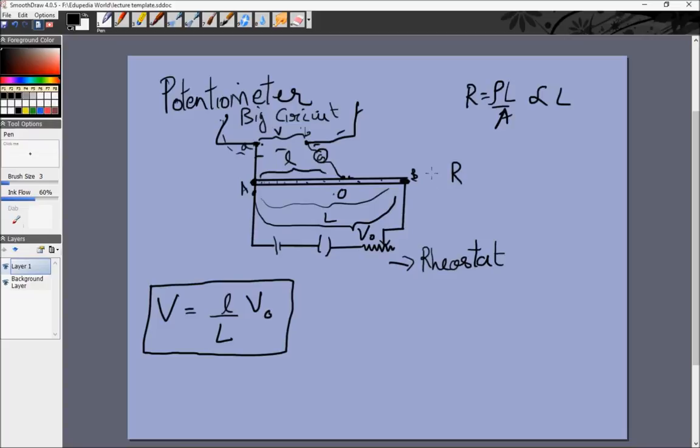Right? Now this V0, sometimes people confuse it for the voltage of this battery. That's not true, because we have a variable resistance as well, so we do not know this; it will be a fraction of that, right? V0 is the potential difference between A and B. Now there's another way to calculate V0. Instead of going through this circuit, we can attach a known potential difference here. So let's say here we attach a battery of EMF E, right? In that case, the length here is L0.